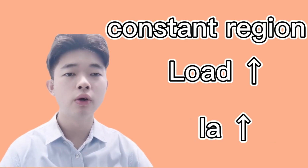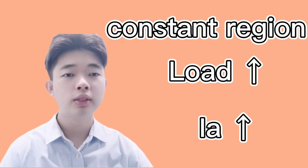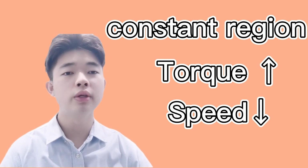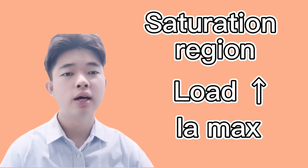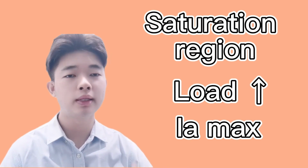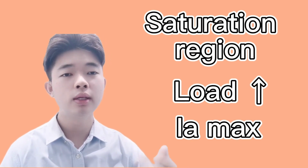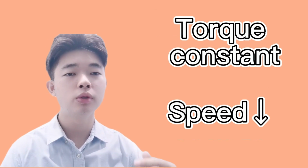As the load on the motor increases, the armature current also increases, which results in a higher torque being produced. The speed of the motor will decrease as the load increases. The third is the saturation region. If the load on the motor continues to increase, the armature current will reach its maximum value, and the motor will enter the saturation region. In this region, the torque produced by the motor will remain constant, and the speed will continue to decrease.